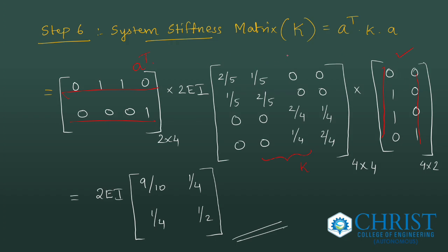So you can substitute this directly in calculator. You can define this as matrix A, this as matrix B, and this as matrix C in calculator. You will directly get this value. This is my capital letter K. While defining, you can also define matrix D along with that. Before finding the calculation, you can define matrix D in calculator as my load matrix. That is P matrix also you can define before solving the problem.